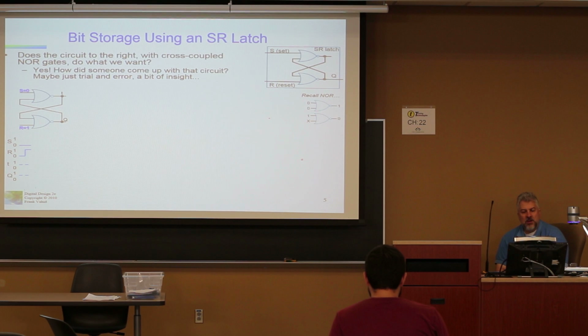All right, here we have 2 inputs. One we'll call S and one we'll call R. Now we really don't know what this T value is here or this Q value is, so we'll just leave that empty, or what we call floating right now. And let's say we change R to go from 0 to 1.